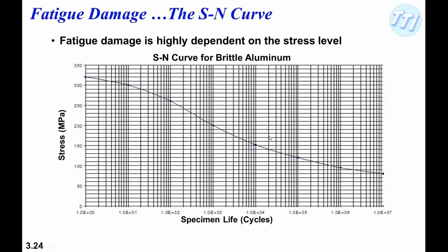At low stress, we wind up out here at 100 megapascals. We wind up having a life that is 10 million cycles, essentially infinite. And as the stress gets lower and lower, we will reach the fatigue limit where the material will last forever.